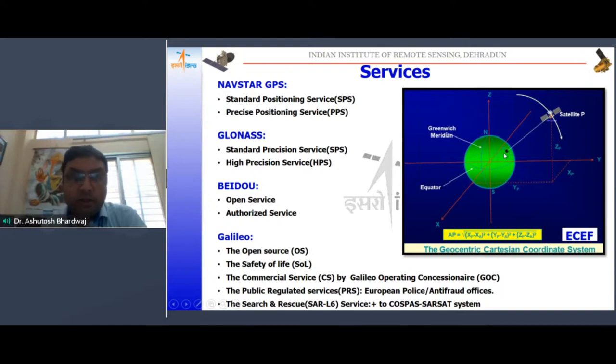Now why is it called pseudo range? Because there are certain errors in the computations. So pseudo means false, range means distance. So instead of calling it a range or the distance, which is the surveying terminology where we refer to the distance as the range, since there are errors in the range, we refer to it as the pseudo range.